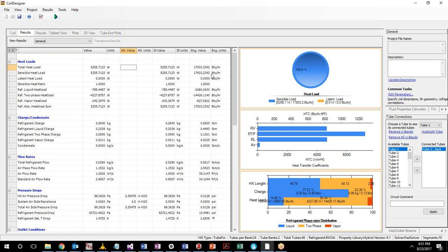But we can also read that into our other software, VapePsych, which allows us to plug in that heat exchanger into an entire vapor compression cycle model. And this would allow us to simulate the impacts of multiple heat exchangers and compressor design changes to evaluate a full heat pump or air conditioner or refrigeration cycle while maintaining all of the modeling detail of one of these very detailed heat exchanger simulations. So that is one of the other extensions of this tool, the ability to not just evaluate the heat exchanger performance, but also the entire cycle's performance.